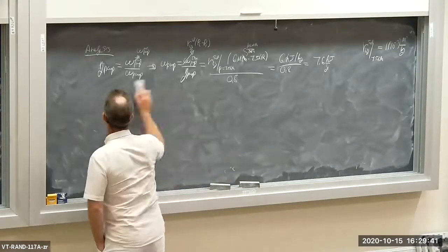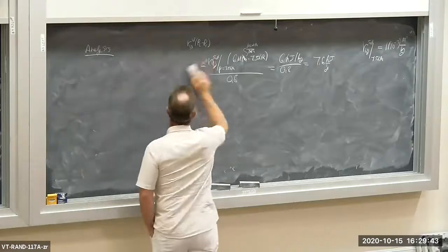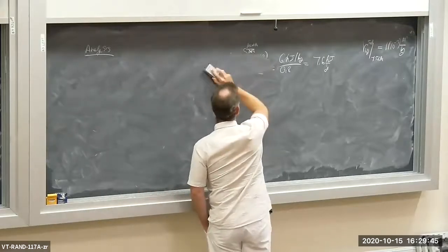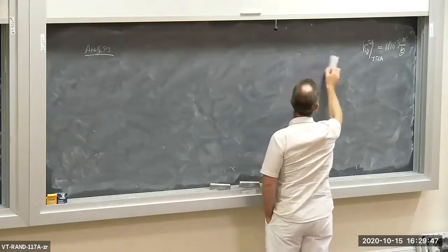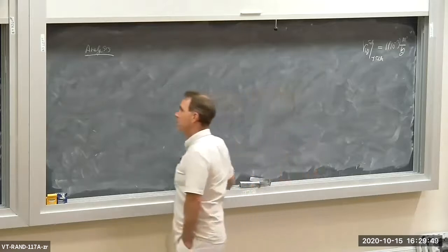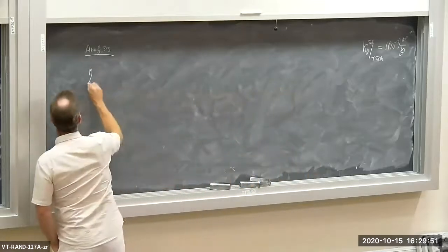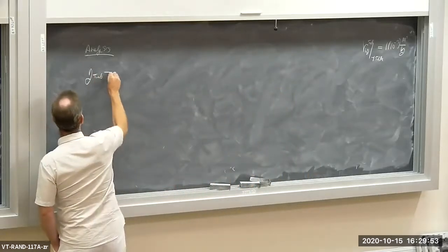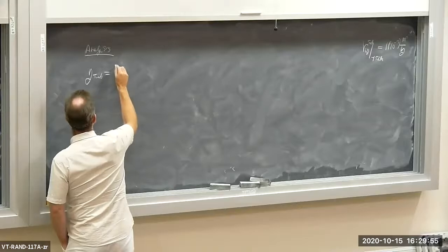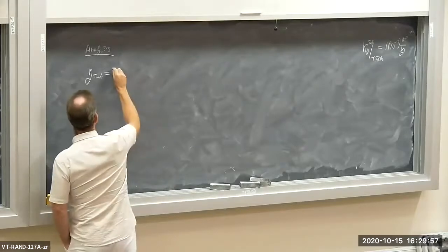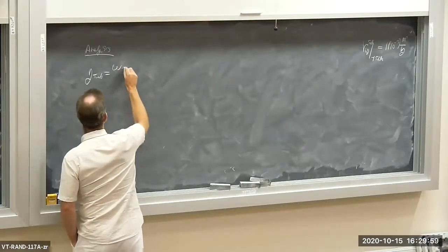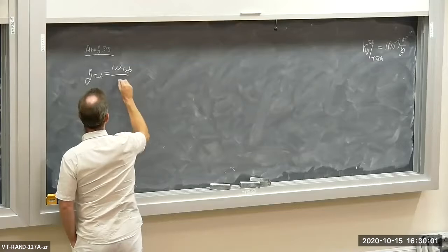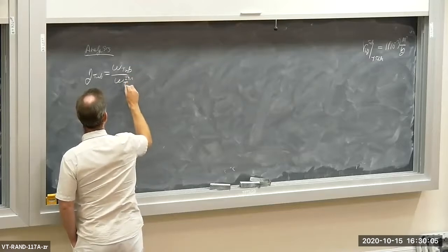So that's going to take a little bit more effort here. So let's use the isentropic efficiency for the turbine. Mass flows are the same for the isentropic and the non-isentropic, so that's the specific work for the real turbine divided by the specific work for the isentropic turbine.